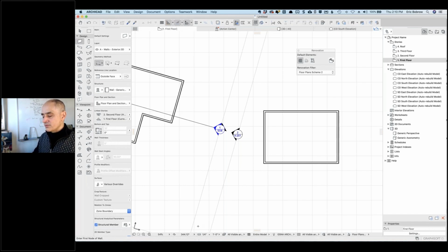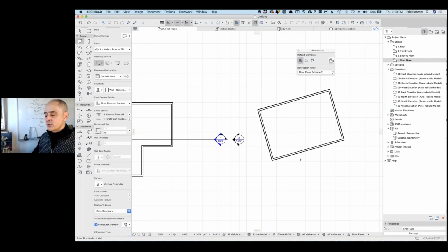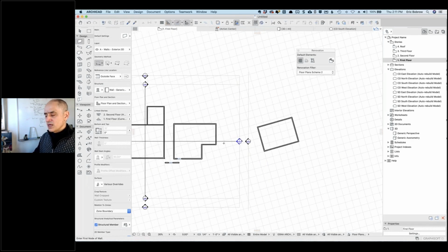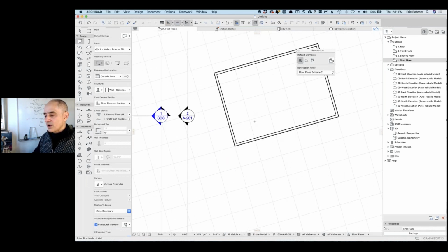Now the grid here, let me just put it back to the 0 here. The grid actually can be rotated separately. And so if I press down where I choose which type of snap I have and say I'd like to set a rotated grid, then I can snap in a similar way. And now the grid is rotated. Now I haven't rotated the view, so I'm seeing things with the normal, quote unquote, orientation, but the grid is rotated. Now, having done that, it will snap.